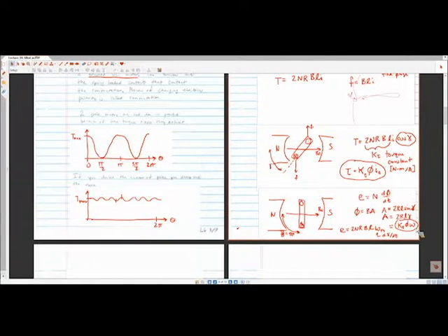Yes? So in physical terms, how does the back EMF affect the motion of the motor? Perfect question to segue into this next part. So it's going to slow down the system, basically. That's one of the fundamental limitations of motors and why they eventually slow down. And if you keep on cranking up the voltage after a certain point, they don't actually go much faster.